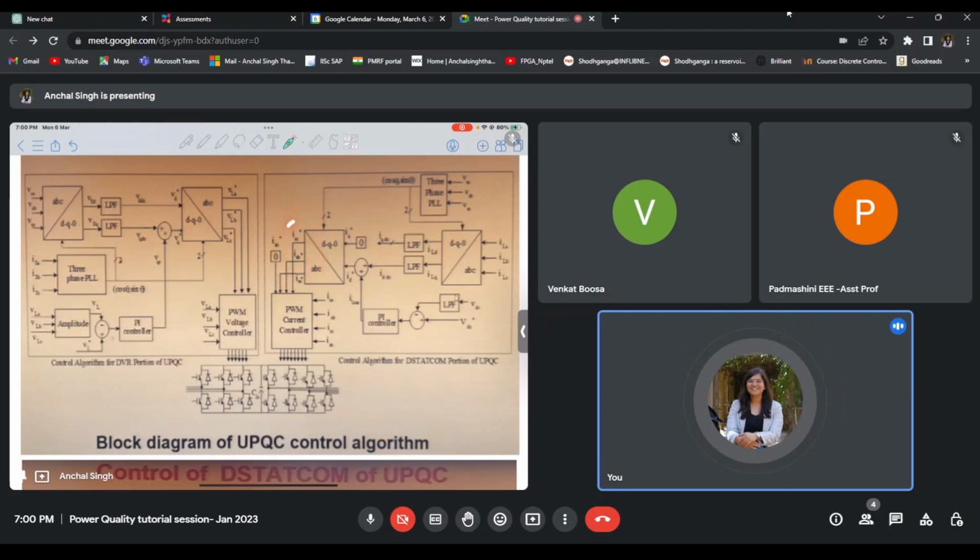It is easier for me to generate this reference than to generate the reference for compensator current, which will be highly nonlinear in nature. Okay. So therefore, I wanted to generate source current references. Now, again, I will be using my load current for generating these references, and in order to get the angle for the DQ0 transformation, I will have a PLL.